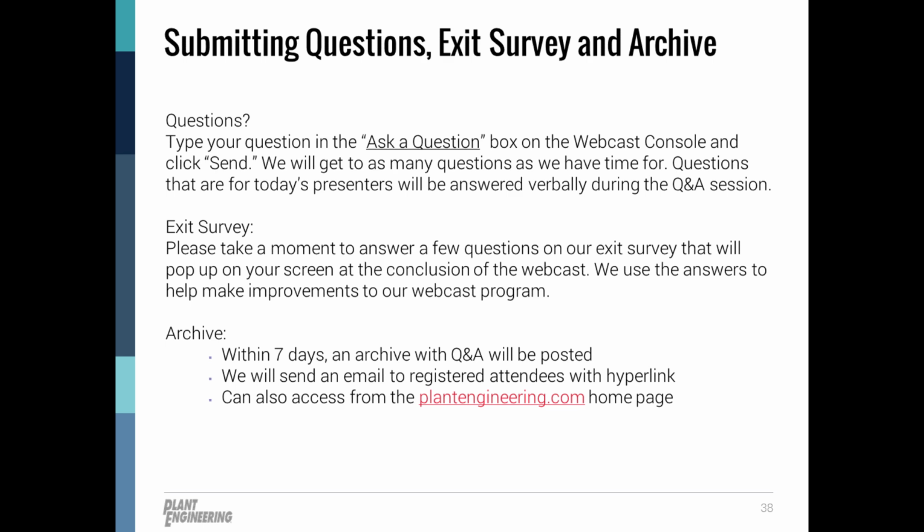Ronnie, where is the best place to start to implement a predictive motor maintenance program? Thanks, Kevin. That's a great question. I would say the best place to start a predictive maintenance program within your plant is with your most critical applications. I would consider those the heart of your plant or process. And then once you have your critical equipment on a regular routine program, you can extend into the rest of your equipment. Just to add, there are also software programs that can assist with your programs, to maintain and keep records for you during that process.